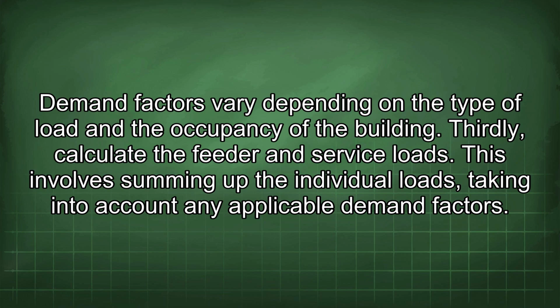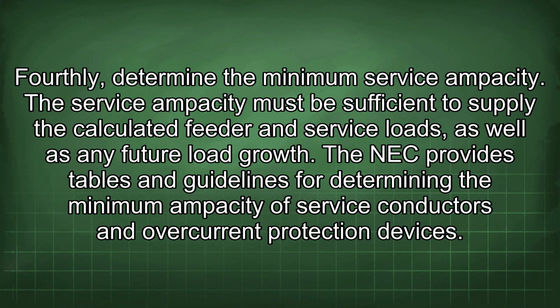This involves summing up the individual loads, taking into account any applicable demand factors. Fourthly, determine the minimum service ampacity. The service ampacity must be sufficient to supply the calculated feeder and service loads, as well as any future load growth. The NEC provides tables and guidelines for determining the minimum ampacity of service conductors and overcurrent protection devices.